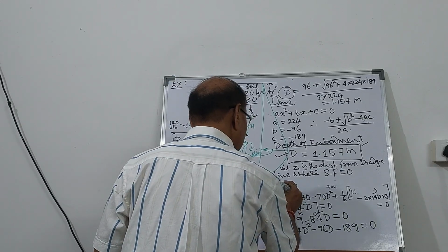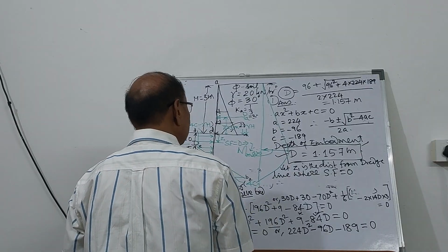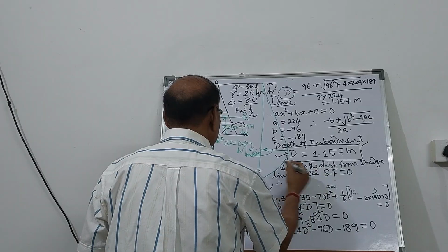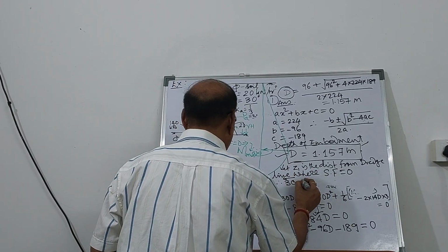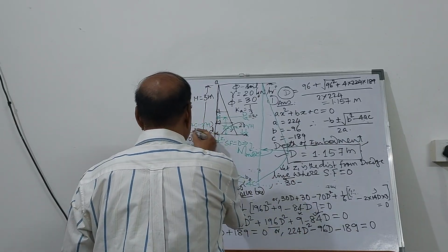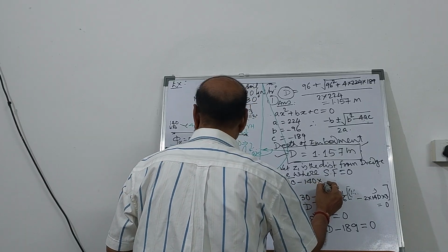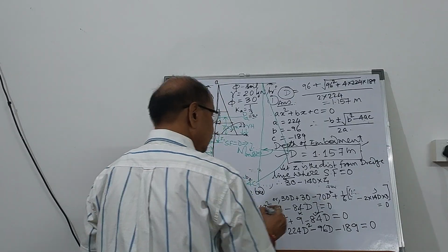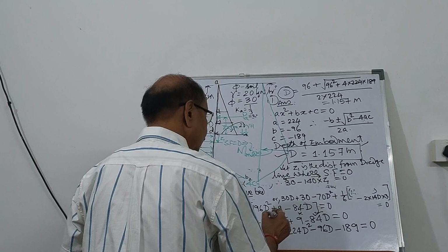Therefore, find out the shear force. This is a cantilever sheet pile, and therefore already you know PA. PA is acting 30 kilonewton, acting this way. So you can find out, this is already known to you, 140 into Z1 is the force that will be acting this way, must be equal to 0.